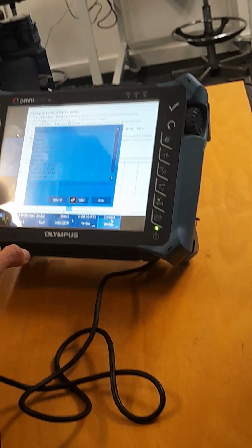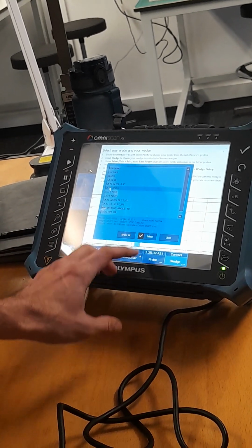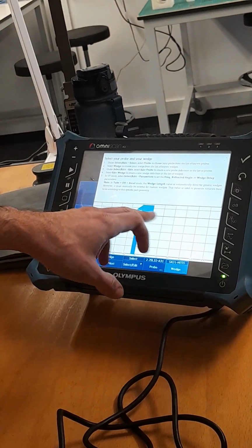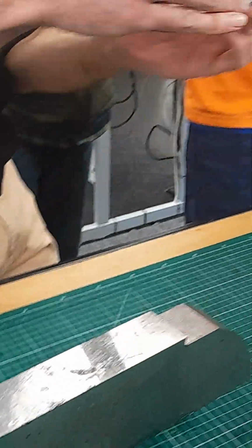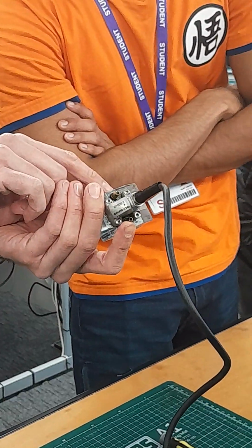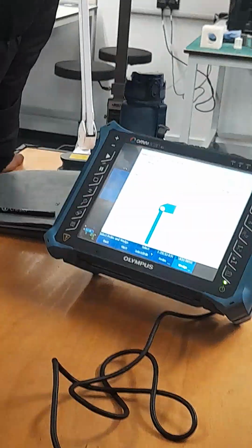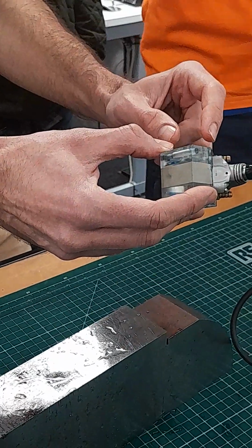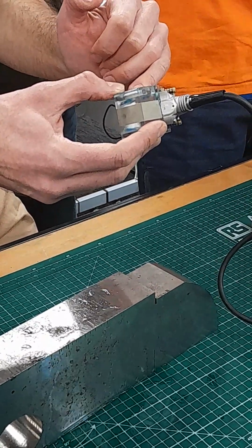So if I go to the wedge library, I can select the N55S. So now this will input into the, it shows me already, it's a 36. So the name of that part is N55S. So now it knows the dimension, it knows that distance, which is important for it to know. The angle 36. So it can show me exact. So now it knows when the beam will hit that interface.